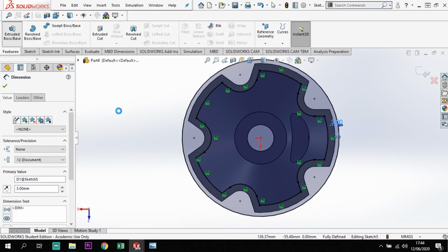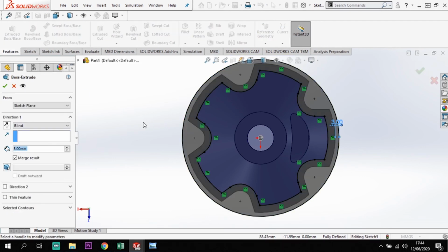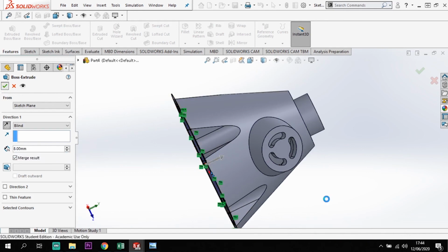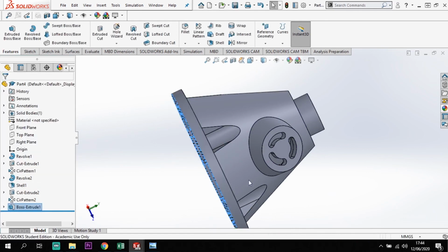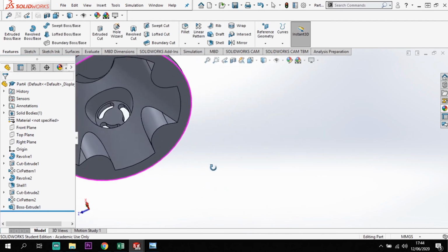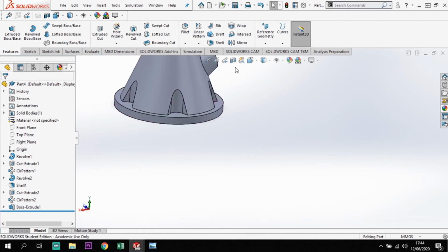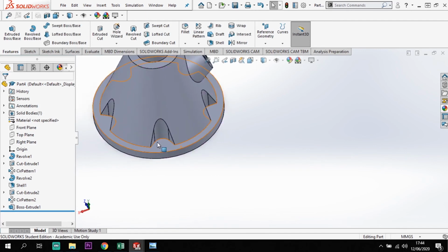Go to the extrude, and I can extrude that shape up by 8mm. Now at the moment it's coming down, I want it to go up, so I'm just going to flip the direction and tick there like so. And we've now got that ring in at the bottom there, and it's not affected our shell at all. Okay. Right, so last bit is just put these cuts through.